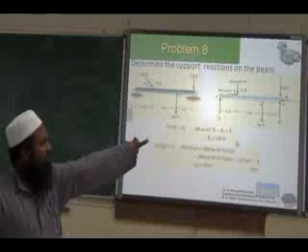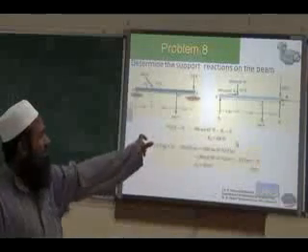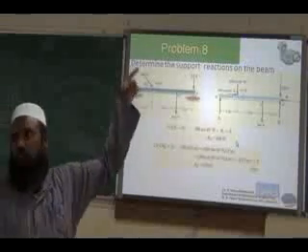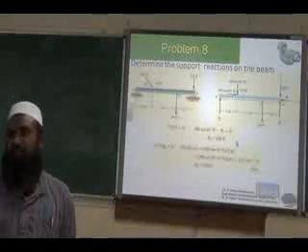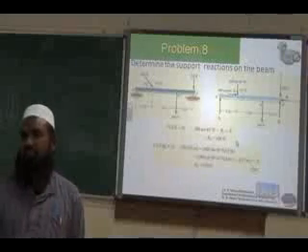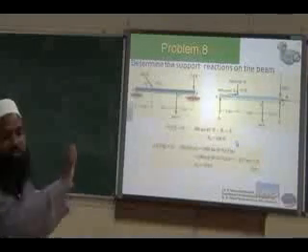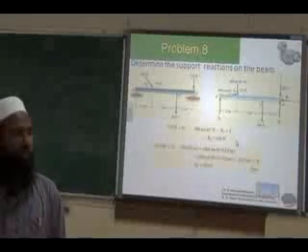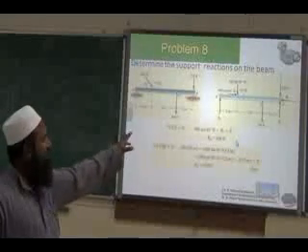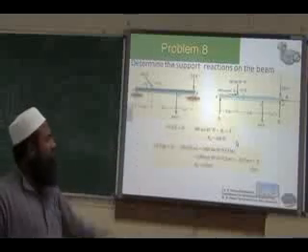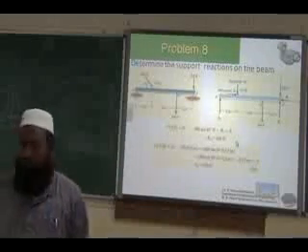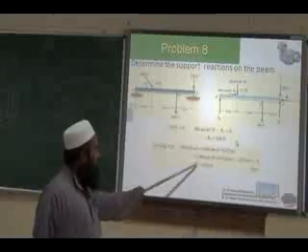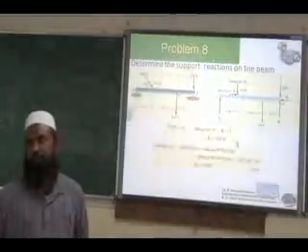So 600 sin 45 times 5 meters, 100 Newton times 2 meters, and 200 Newton is passing through B. So its moment is 0. The distance of the force from B is 0. So 200 Newton and By will not have any moment when you take moment about B. Okay. So only the three forces Ay, 600 sin 45 and 100 Newton will create moment. So we got the moment equation about B, from which we can find out the unknown Ay.